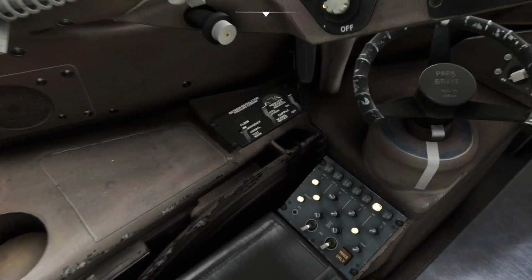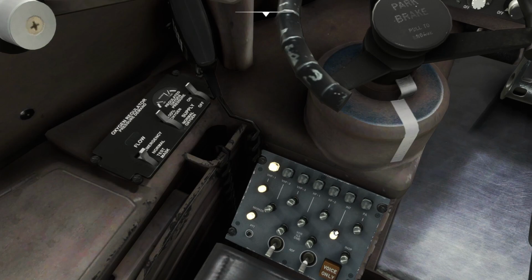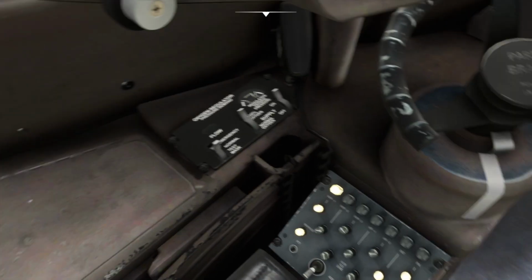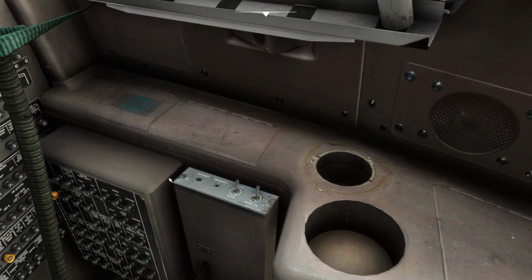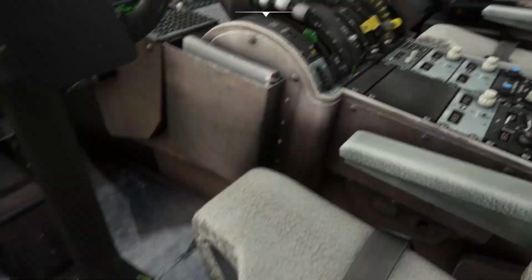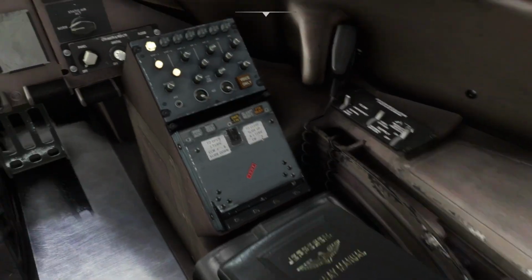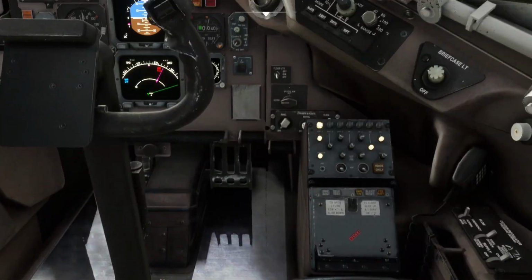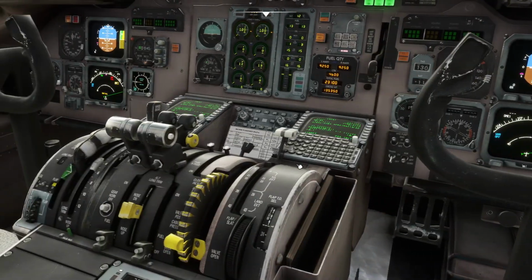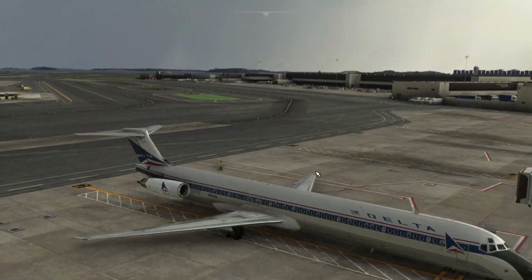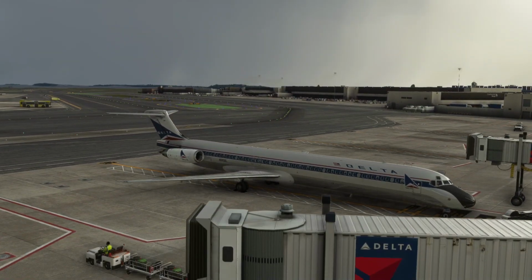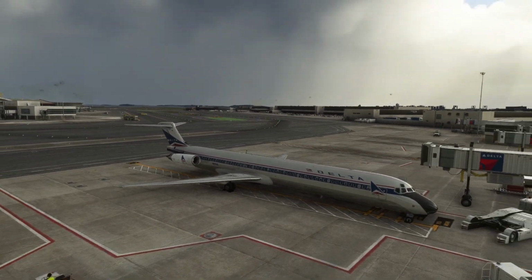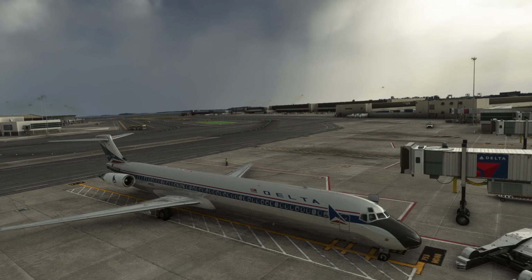Coming down here, we can set up the VHF panel for the captain, which is VHF 100 from PA marker. Move this to test the oxygen, make sure the oxygen supply is on, 100% oxygen indicated. And yeah, checking that all the emergency equipment is on board if you're that kind of person. Same configuration, as well as testing it. So that's all nice and good. So I think that right about now we are in a fit state to check out the FMS on board this aircraft.